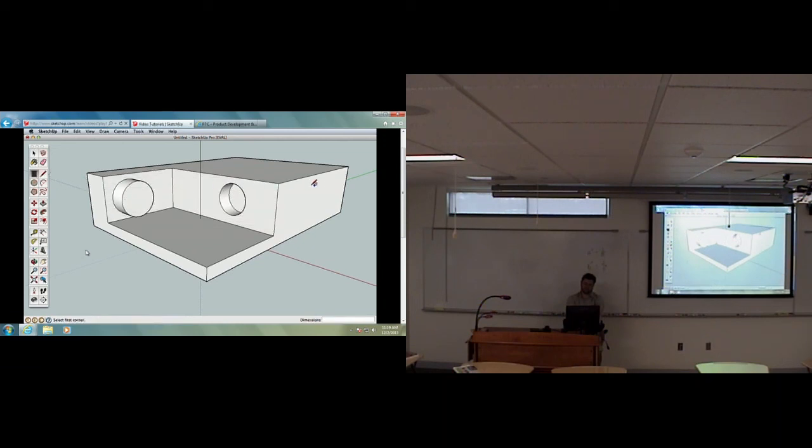Select the rectangle tool again and start from this upper edge. SketchUp shows a red dot indicating you are on the edge. Click to start and draw down to a lower edge, also showing a red dot. Use Push-Pull to push this surface inward.